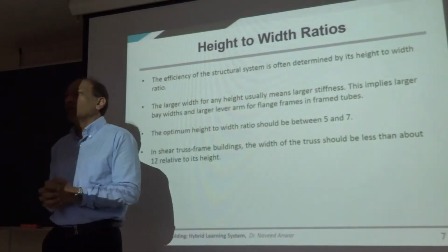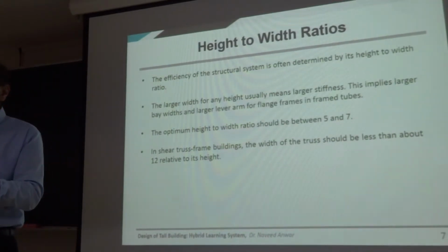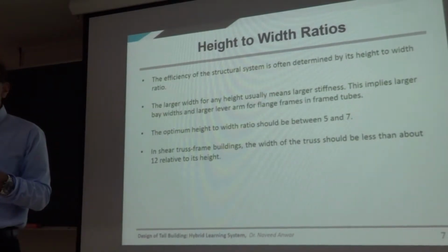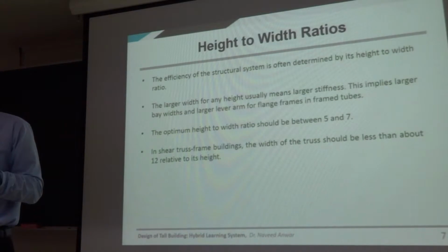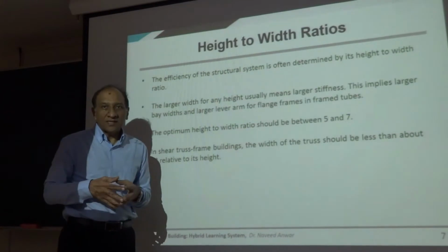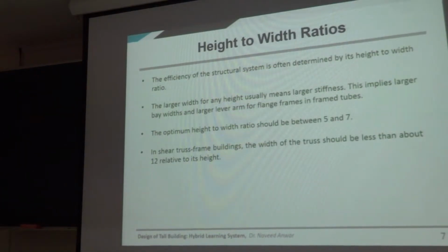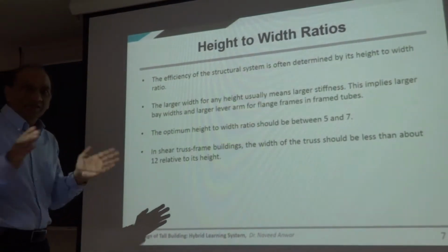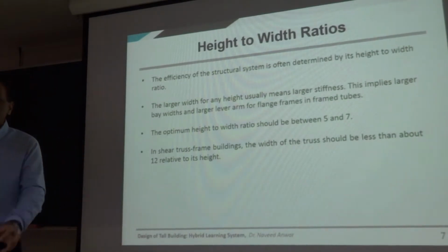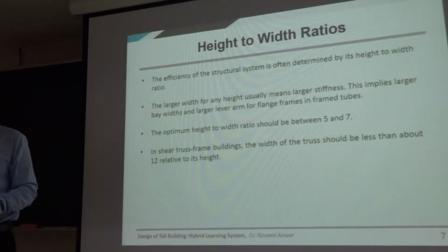But almost no tall building does that. Why? Because the contractor has to make new formwork every 10 floors. Everything has to be changed, and it becomes uneconomical on that side. So your optimum solution, which looks very good on one side, becomes unoptimum. The window sizes have to be changed, the cladding system has to be changed, the fixing has to be changed, everything has to be changed when you change the column size, and nobody likes that. They want quick construction, straight. So you end up having a highly non-optimized column, but an overall optimized building.